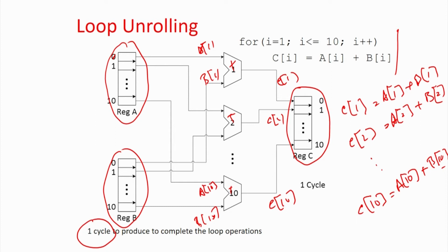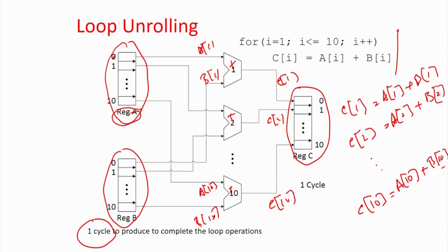And there are two things to note here. The first thing is that this is no more a memory, because when you map something to memory, I do not have access to 10 accesses at the same time. In memory you can have a maximum of 1 or 2 accesses, because the memory has a port and you have to access the memory through that port, read port and write port. So, whenever you have more accesses, you cannot map this array to memory, it will be mapped to registers and you are reading all these 10 data in parallel.